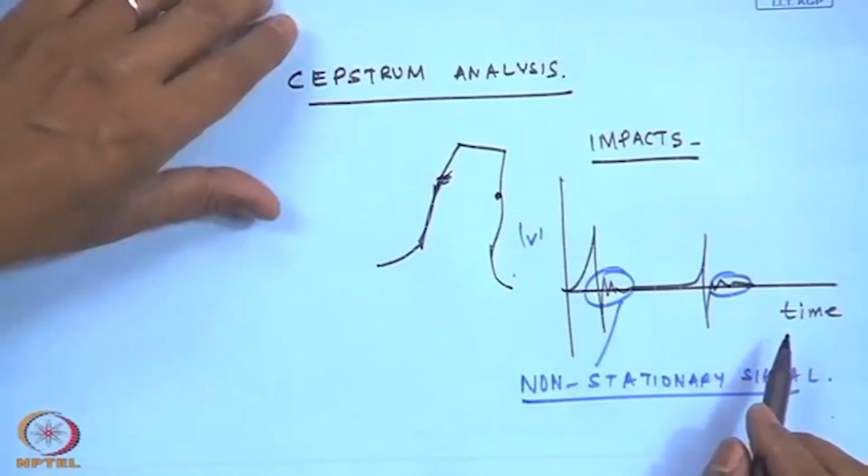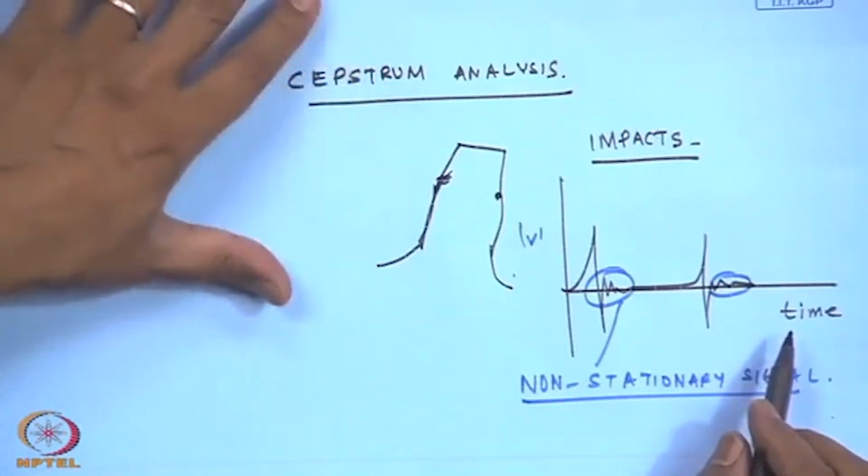So, the fundamental signal processing theorems of stationary signals, wherein the properties of the single ensemble over a given time change is being violated, and thus stationary signal analysis like FFT etc., cannot be done on such signals. So, we have to do signal analysis using certain non-stationary methods like the wavelets.